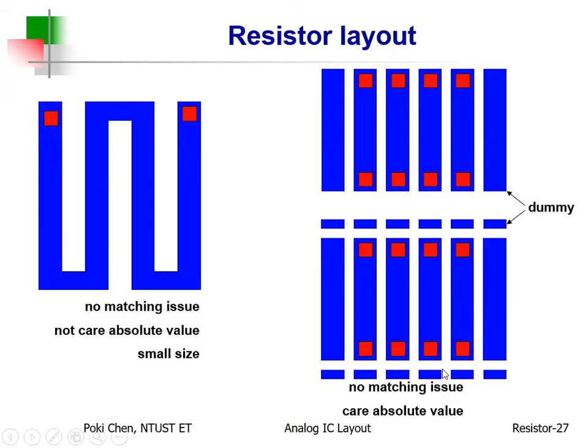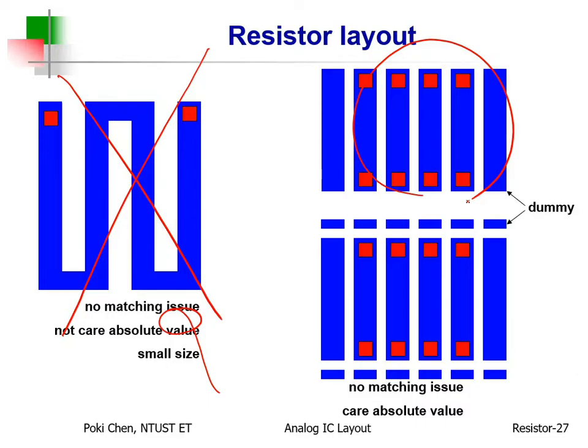And then, for resistor layout, if you would like to get the largest resistance, maybe you think such kind of serpentine layout will be good for you, right? However, according to accuracy, I strongly do not recommend it. Don't do it. Even if you need high resistance, do something like this. Okay? Then connect them in series. Connect here, connect there. In this way, you can achieve the resistor with much more accurate resistance.